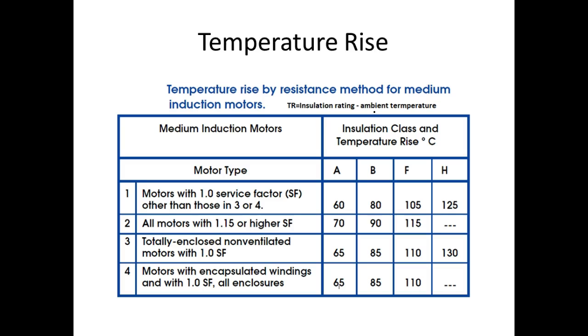Motors with encapsulated windings. This is very popular because those windings try to vibrate all the time, since they have AC on them, right? This is why transformers hum and AC motors hum. When this is the north, this is the south, the windings have a tendency to come together, and then when it goes to 0, they have a tendency to spring apart. That's why transformers hum.